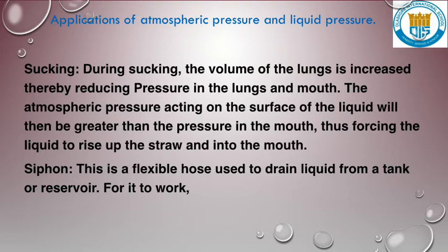You're taking a drink through a straw. When you suck on the straw, the volume of your lungs is increased and pressure is reduced in the lungs and mouth. Then the atmospheric pressure acting on the surface of the liquid will then be greater than the pressure in the mouth. So it's able to draw up the liquid.